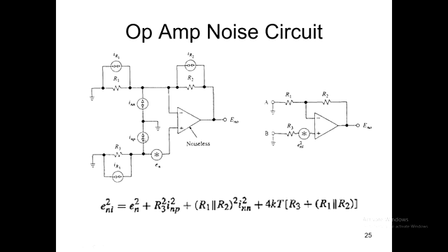That current flowing through that resistor. Here it is. This current flowing through those two resistors, one bit going that way, one bit going that way. So we're really thinking of those two resistors in parallel, because we're thinking of this as being grounded internally through the driving voltage source of the op-amp. Here it is. And then there's the thermal noise of the resistors by themselves,